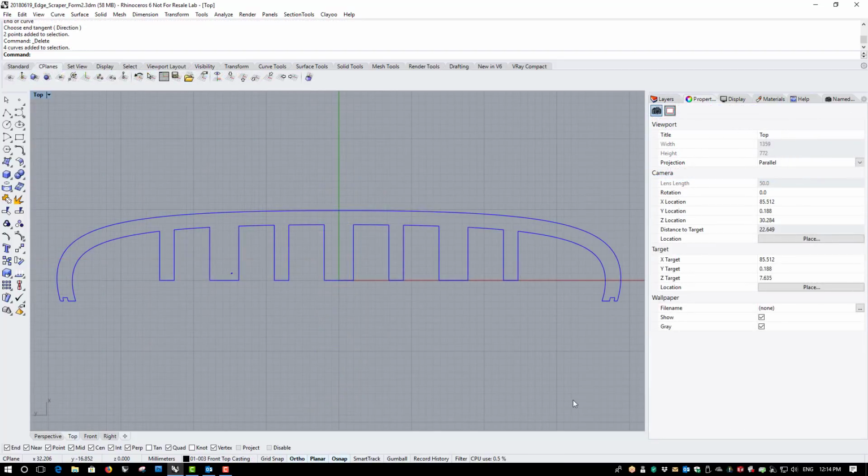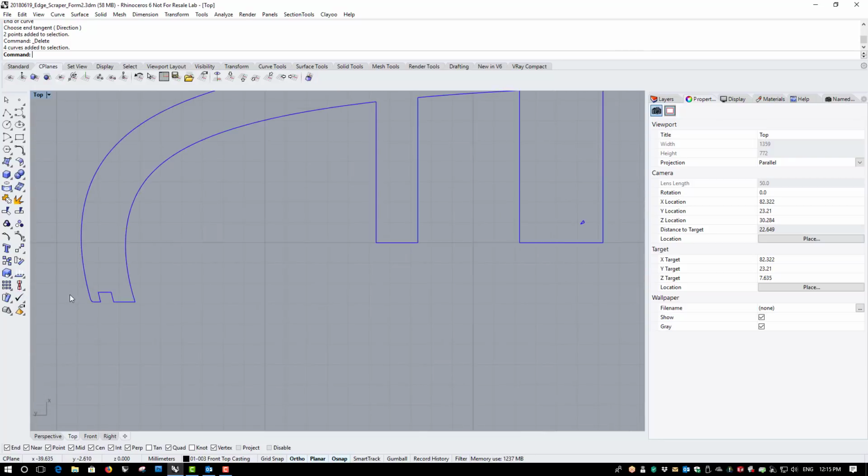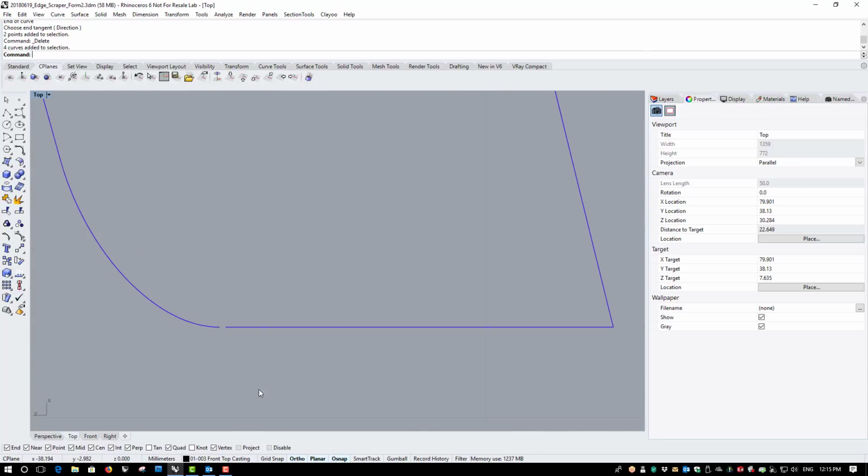If we look at this one curve in more detail, I'll try to explain the three main issues you would see when an STL file is not valid. The first and probably the most common issue is when you have edges on the surface that are not joined together. This, of course, if we look at a slice through the model, will create a gap here in the description of the closed volume, and this will cause your STL file to fail.